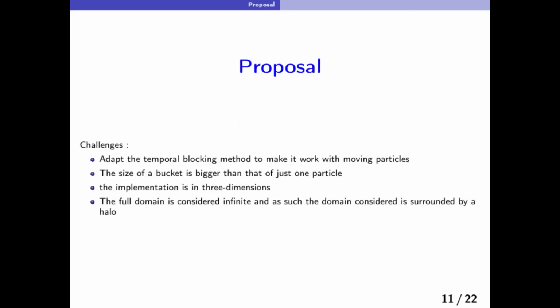Our proposal is to adapt the temporal method to use it with the moving particles in MPS. The difference is that a bucket contains multiple particles that can freely move between the buckets. Also, the implementation is in 3 dimensions, even though the figures are presented in 2 dimensions for clarity of presentation.